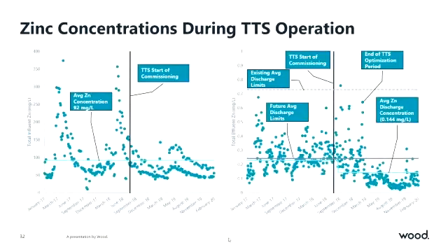So, the performance and cost of the system. This was that same influent zinc figure we looked at previously, just extended after the start of commissioning of the temporary system. You can see it's still dealing with a lot of variability in zinc. We didn't quite have as bad of a spring freshet this year, so we didn't have as big of a spike, but still around 92 milligrams per liter coming in to the plant.